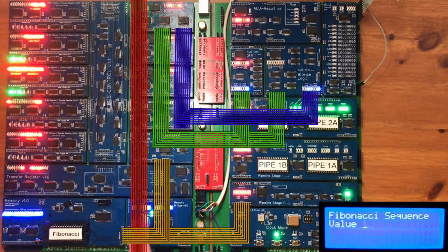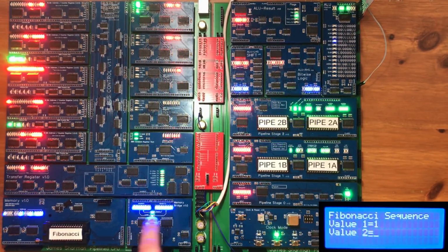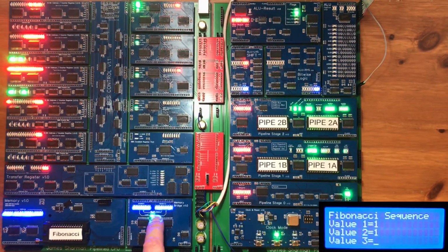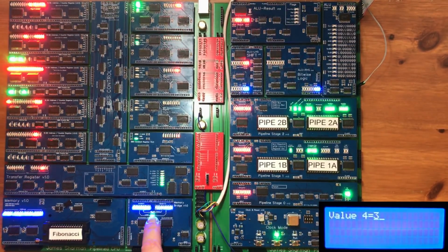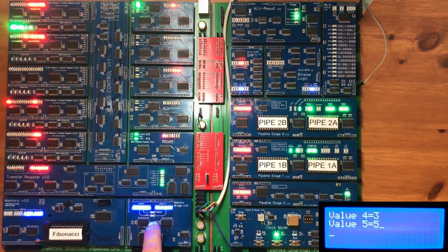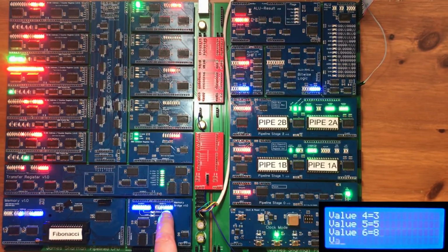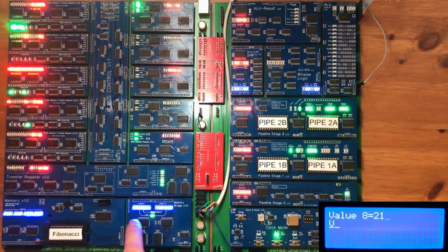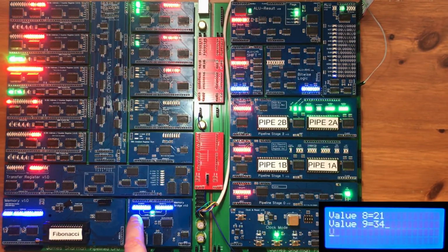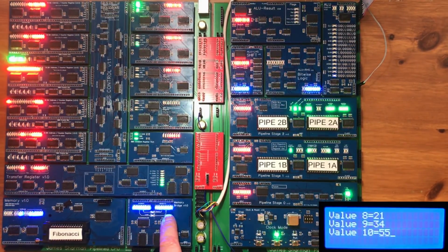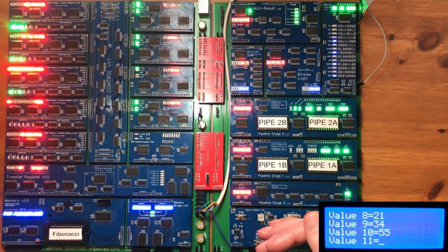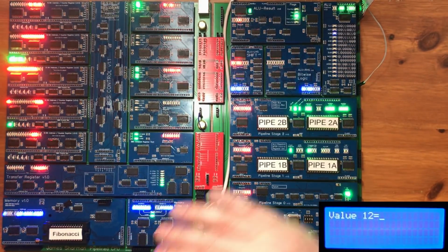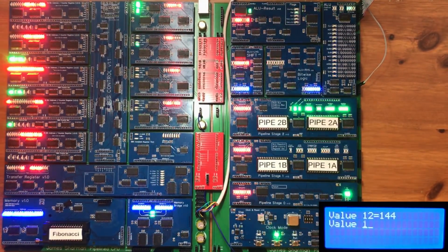So I conveniently have both the main bus and mem data being displayed in the memory bridge here. And then you've got 2 LEDs here which will give you a signal to show if the memory bridge is pulling data from mem data and inserting it onto main bus, or if it's taking the data from main bus and pushing it onto mem data, which is the reverse operation, which is what's going on when the processor is writing to RAM.